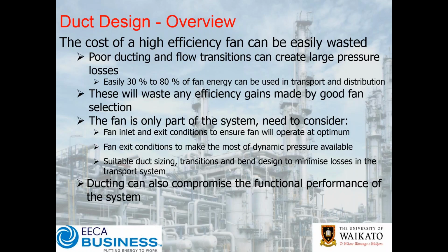So the fan is only part of the system, so we need to consider in particular the inlet and exit conditions of the fan. So very, very important here. Can't emphasize this enough. You can once again spend all this money on having a really good quality fan, but then if you put a really bad fan intake, a poorly designed inlet filter bank, for example, you can compromise the performance of that fan.